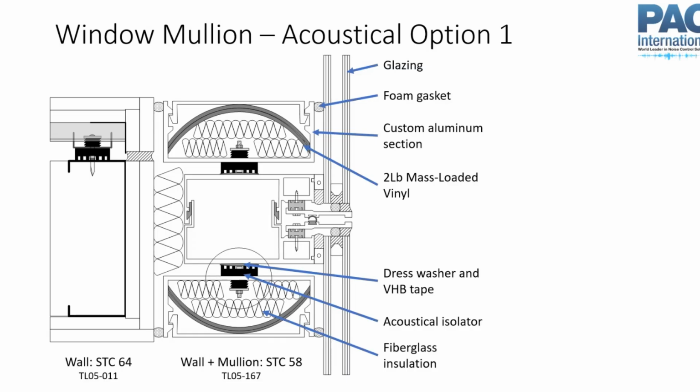If you have a thin wall and you have back-to-back electrical boxes, they could touch each other. And if you've got acoustic isolation in that wall, you've now short-circuited it because, again, you've created this rigid path. So again, you just want to get out your pencil and trace it. Do I have a rigid path all the way through? If so, that's an issue, and you need to figure out how to disconnect it.